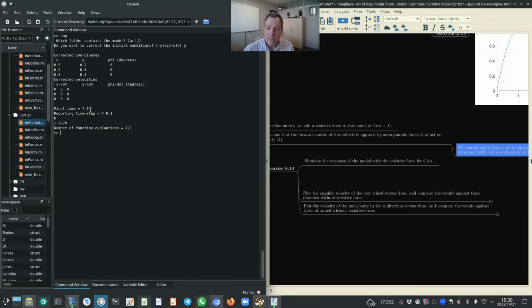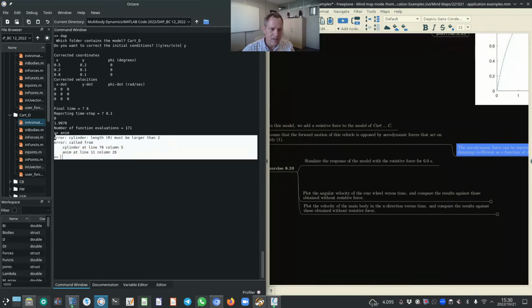Okay, now once again as a sanity check, let's do the animation. So we type in the abbreviation anim for animation. Okay, there's the error. Maybe this is good, it happens. This is the error that you get when R in the input file in animate is not specified as 2 values.